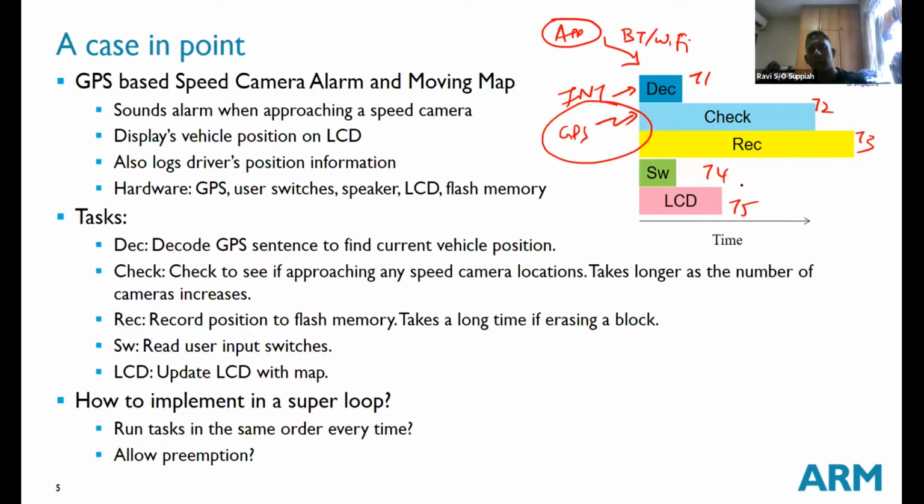All right, so I need to now get inputs from another device as well. Okay, so I can also factor that in very nicely with an RTOS framework, instead of trying to see where do I insert a new function or where do I break the code and things like that. Okay, so that is the good part of switching to an RTOS environment, the scalability factor.